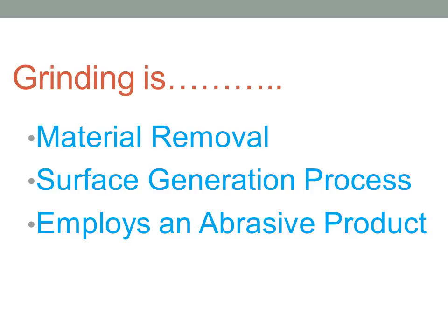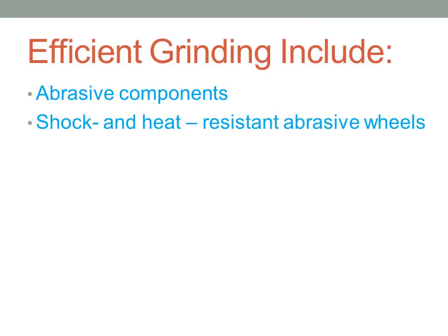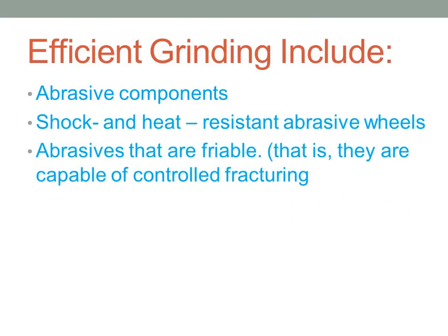The requirements for efficient grinding include abrasive components which are harder than the work, shock and heat resistant abrasive wheels, and the third one, abrasives that are friable. That is, they are capable of controlled fracturing.